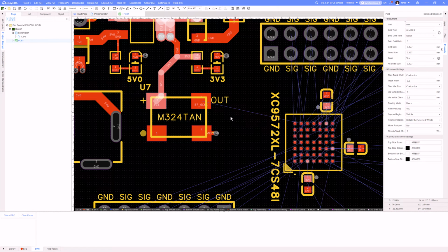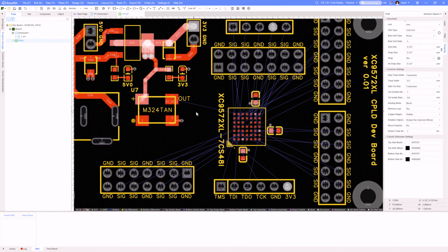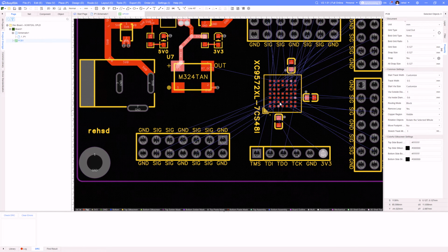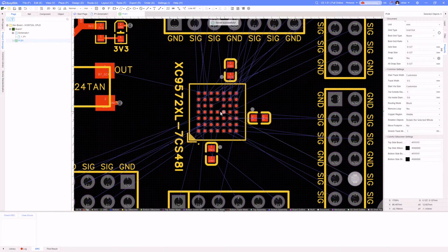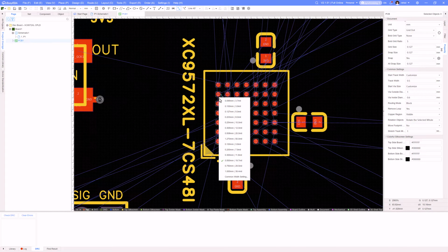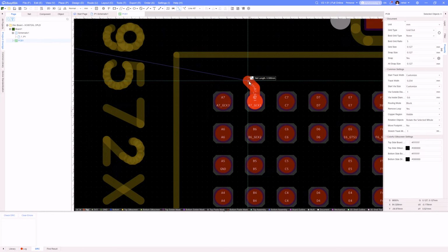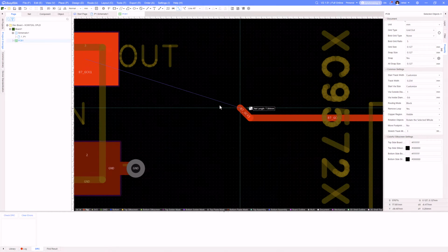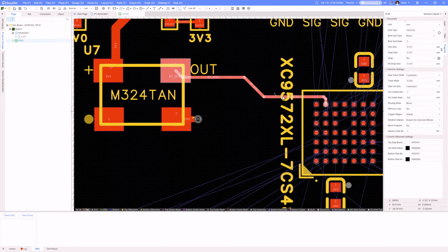This is my clock out of this oscillator. That needs to go, it looks like, to this pin here. So this is now going to start getting me into my BGA here, where I'm going to have to start connecting all those signals, sorry. If I look at that, okay, let's draw a wire, and I want to choose the size. So let's just say I pick a 0.254, and I look at that clock and, oh yeah, I can do that and get this connected over in a way that I think makes sense.